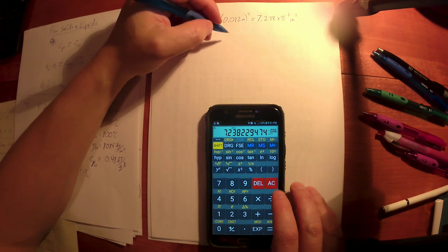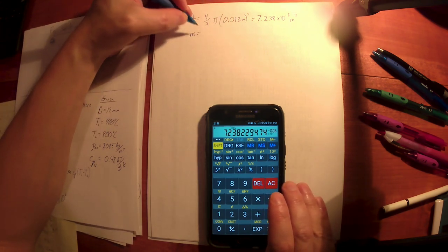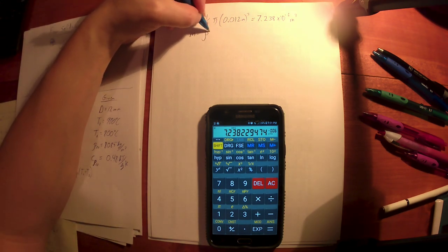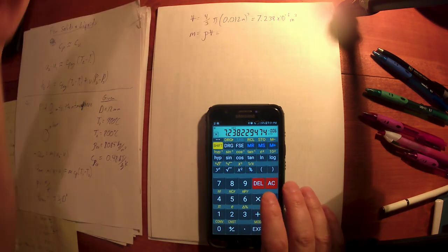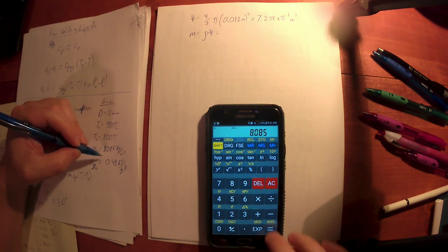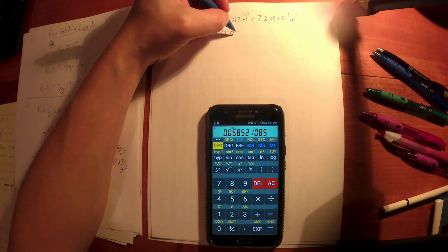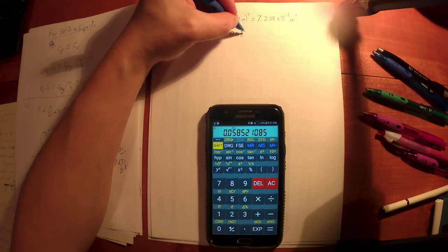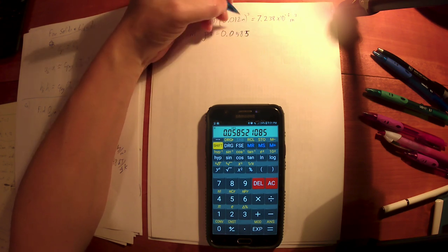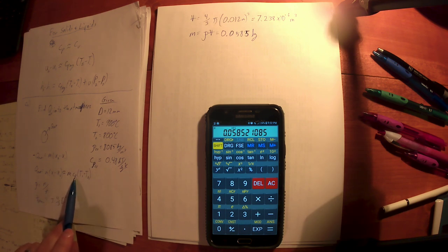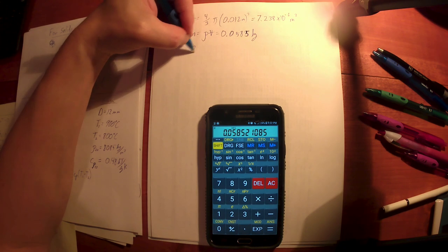Meters cubed are enormous. Okay, the mass, I said over here, that if I take volume times the density, that gives me the mass. So multiply this by the 8085 density. That means each one of these ball bearings has about 60 grams of mass. It's 0.0585 kilograms. Okay, so this is done. We're up to here now. I know the mass. I've got C sub P given. I know the temperatures. Just compute.